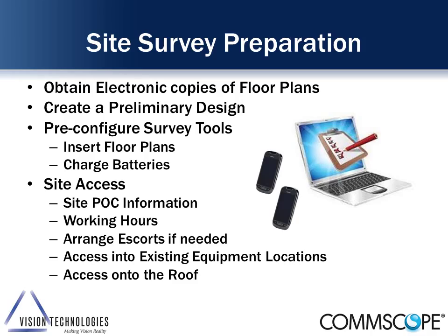Part of that's inserting the floor plans into the survey PC or tablet, making sure that the batteries for all the devices are charged, making sure that we have whether we're going to do a backpack-based survey, whether we're going to use a cart with wheels and have the tools and equipment on a mobile cart, are all things we need to properly prepare for. As Ron talked about, site access is important.